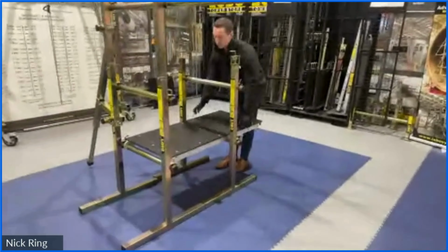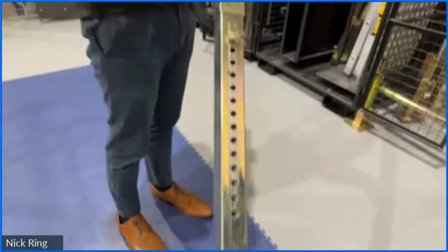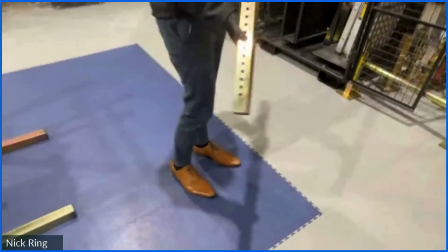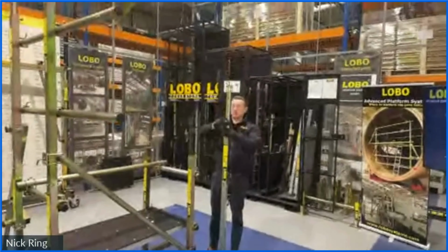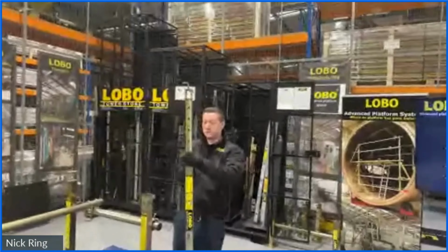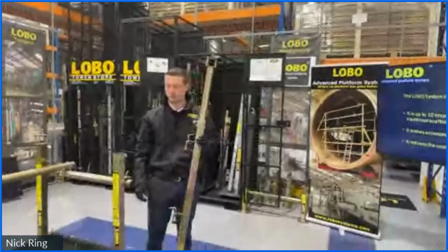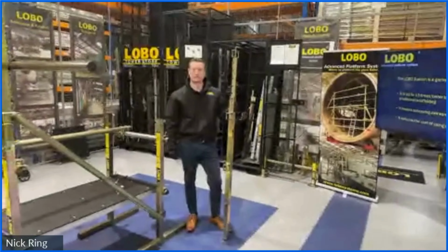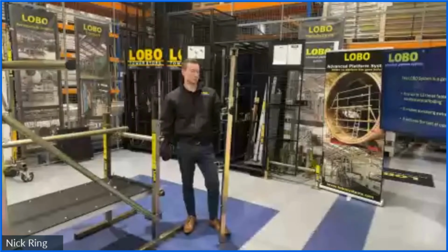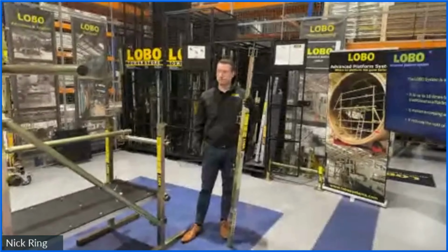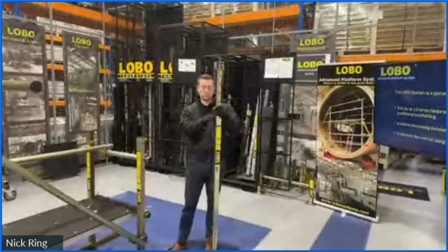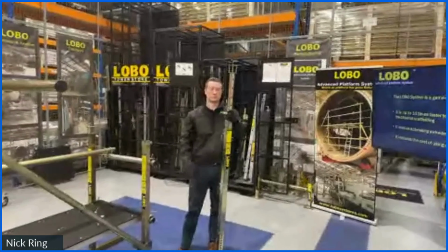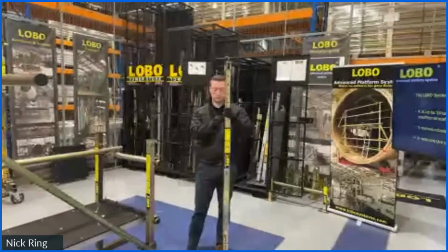Okay, to go higher, we need to use this. This is an extension, and at the bottom, it's adjustable. So to fit this, we invoke a process that we're fully trained on when we come to train you, and it's known as the advanced guardrail process. So there's the advanced guardrail going in the top. What it really means is we give you a very, very safe way to build the system by always having a guardrail in advance of you. So therefore, you should never be exposed to the risk of a fall. And in certain cases, your safety department should be able to risk assess out the requirement for lanyards.